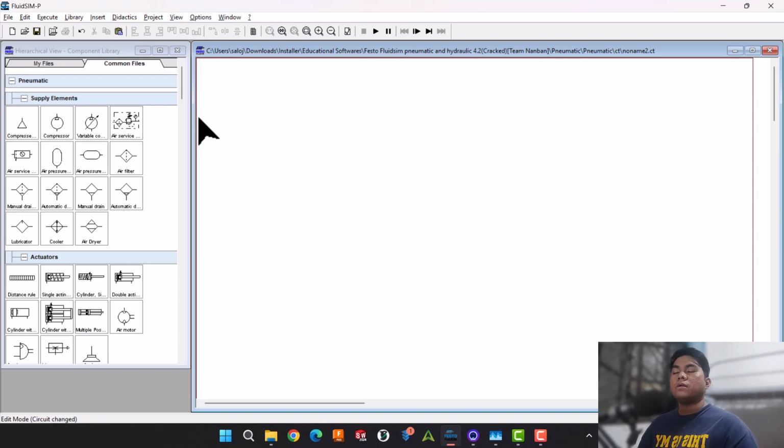So for example, cylinders and limit switches are called field devices, so they are far away from our control board or the control panel of our pneumatic systems, especially in companies. So instead of just using basic pneumatic components or mechanical components to create pneumatic systems, we use electro pneumatics in order for us to create such a system na may control tayo far away from our field devices.